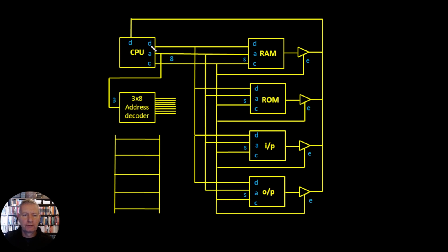Now I've just called the bus D, so D for data, and there's going to be an input here. So that's the input of the bus, and that's the output of the bus. Now we know that we've got an input-output here in this instance because Logisim doesn't allow us to have a single pin which we can use for input-output. We have to separate them, so that's why these are separated. So we have our output data, and the data passes into the RAM.